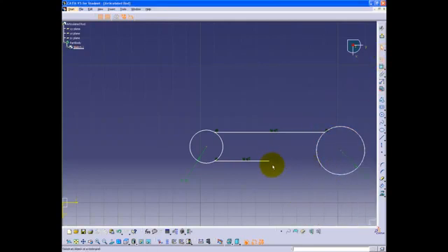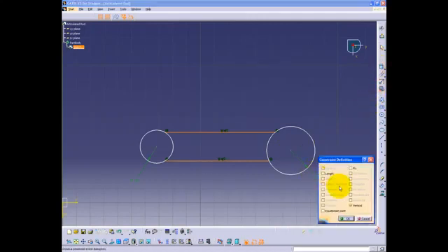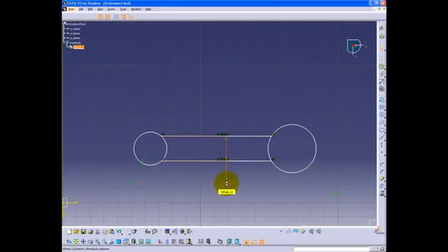It is important here to select the two lines before the center of the circle. Do the same steps for the 17.5mm radius circle as done on the 12mm radius circle. The space between the two lines is 18mm. Click the Constraint button and select the two lines. Double-click on the green constraint and change the value to 18. Do the same for the center points of the two circles.